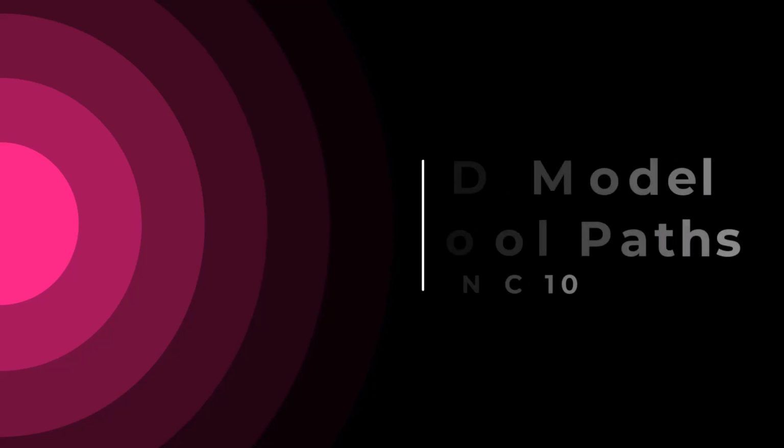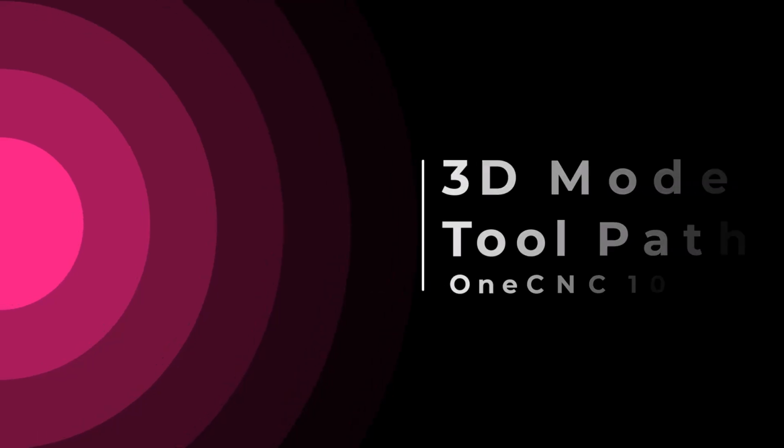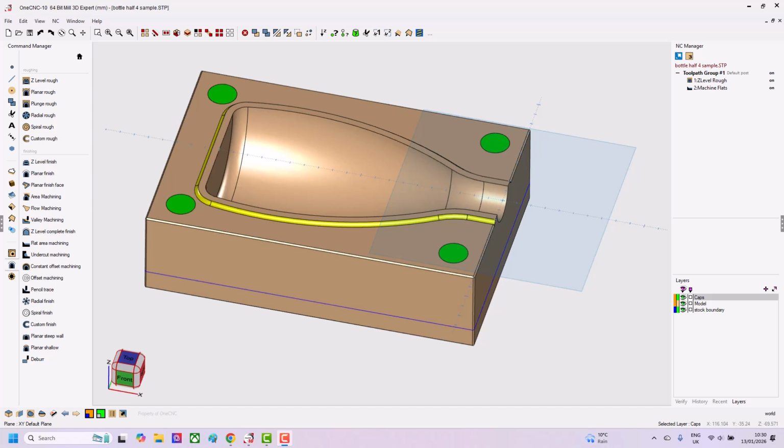In this section of the video, we're going to take a look at just some of the 3D model toolpaths available in OneCNC 10, starting with pencil trace and area machining. In this example, I have already roughed this part out using Z-level high speed open and finished the top face and plateau using flat area machining, two toolpaths that you will be familiar with. For machining the 2.5mm radius, which in this example is a full radius highlighted in yellow, we'll be using pencil trace.